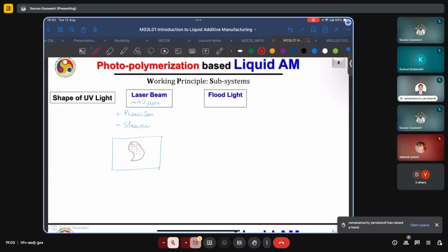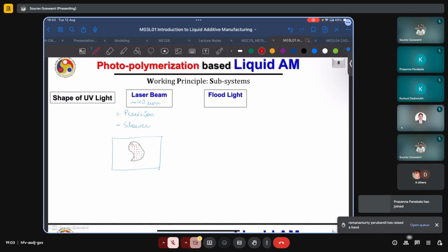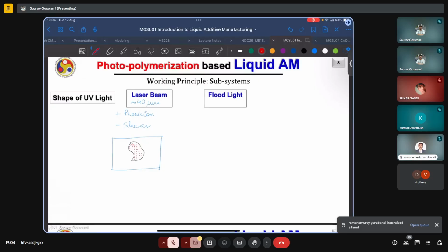For some of us who are into R&D and who might have used a technique called EBSD, where again you scan an area but you do it line by line, you would be familiar with how long it takes. Even with the most updated technology, depending on your detector type, even for areas as small as 100 by 100 microns, the scan time for a good enough resolution can easily run into a couple of hours.